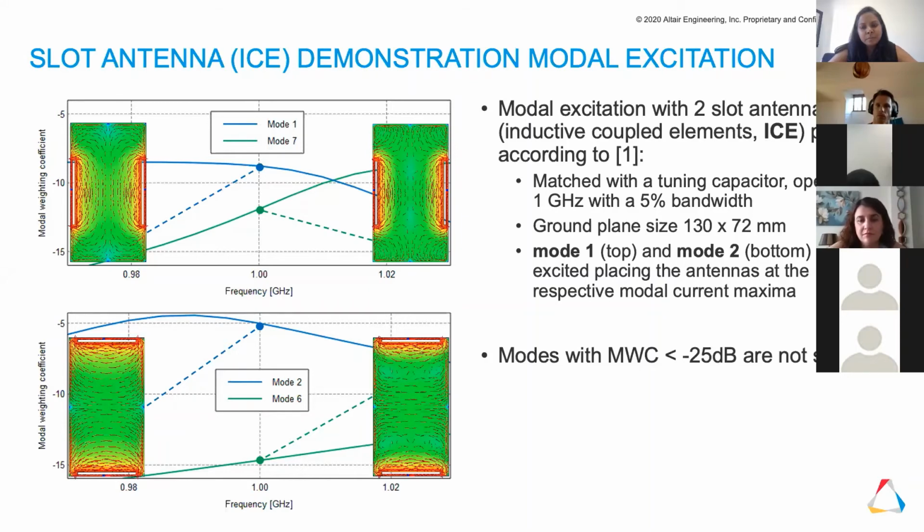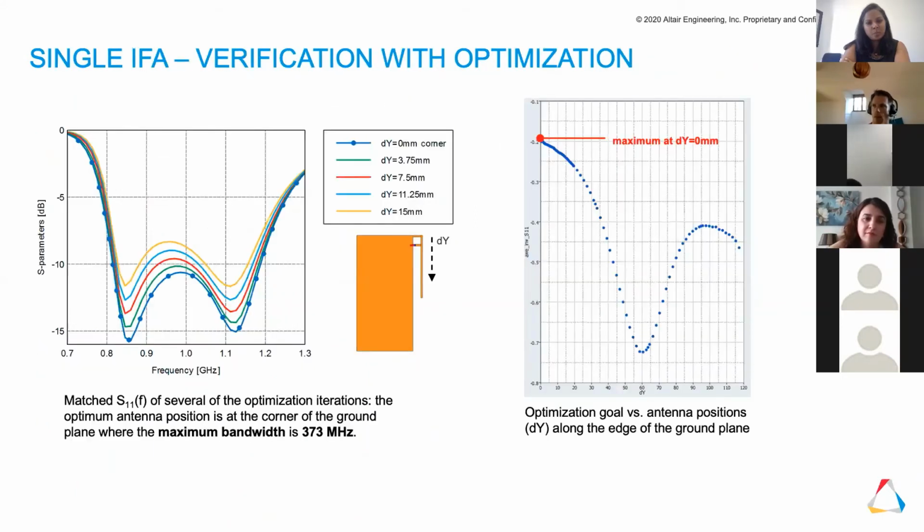Yeah, but I was thinking, since then you are using fewer exciters than, let's say, the number that is required to purely excite the mode. And then you were showing that you were moving at some point the position of the exciter to get the widest possible band. So I was wondering if this parametric study is really necessary, and then you optimize the actual one as you show, or if there is a way to exploit the characteristic mode analysis in order to avoid this. Sorry, maybe I wasn't clear enough yet.